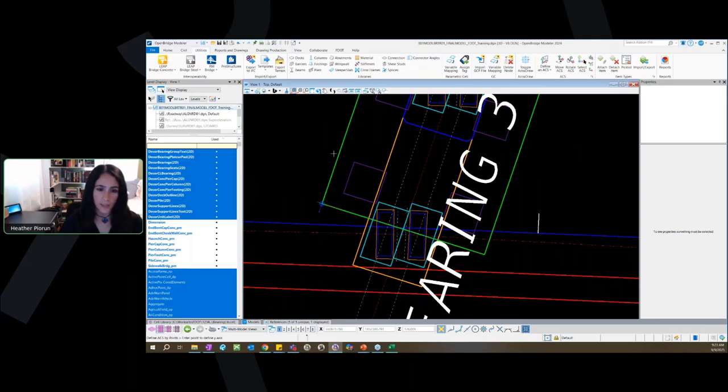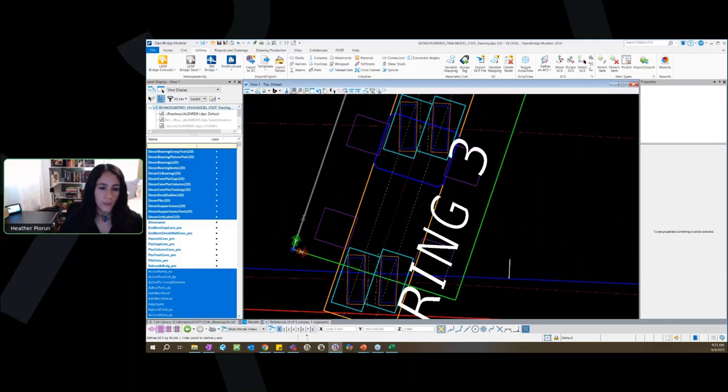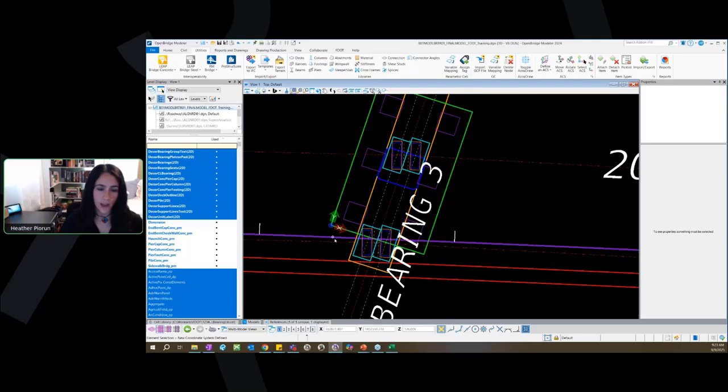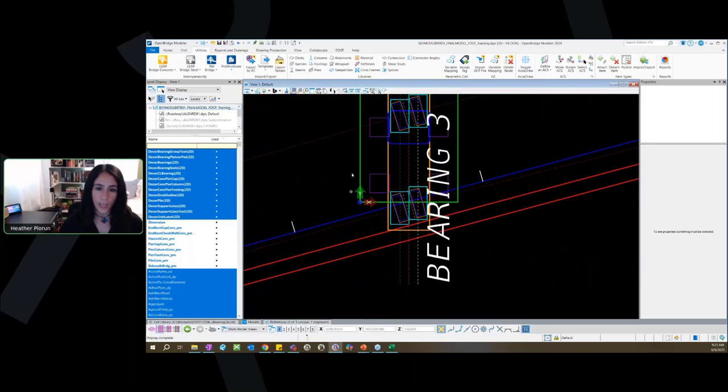So now that we've set the X-axis, obviously the Y-axis could, in theory, be anywhere, in and out of the page or on the page. So we want to define it on the page here. So we want it to just be along the other axis of our footing. So now I can click on the axis of the footing, and now you can see the ACS has been defined here. And what that is helpful for is now, if I went Shift, right click, either hit T for top, or it's also up here for view rotation. If I click and hold, go down to top view. Now, when I do that view, it's going to have it oriented along the ACS.